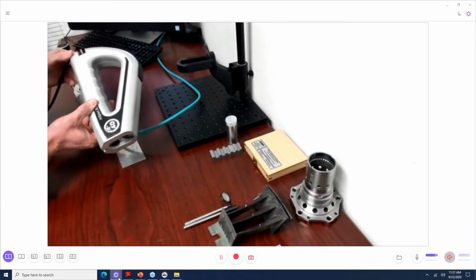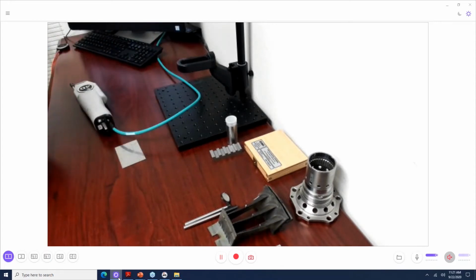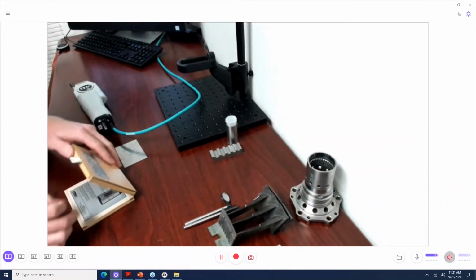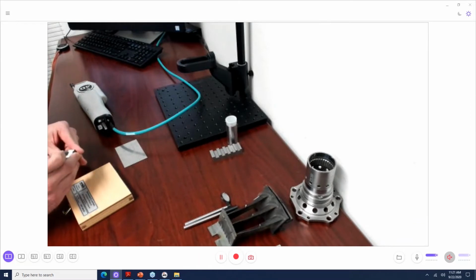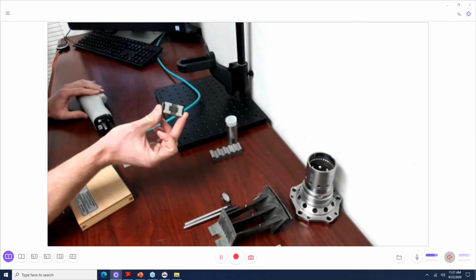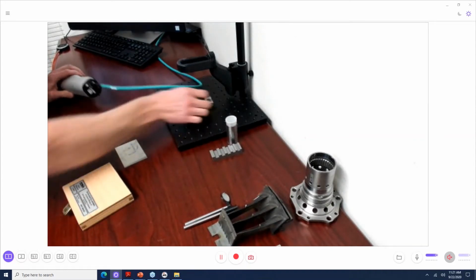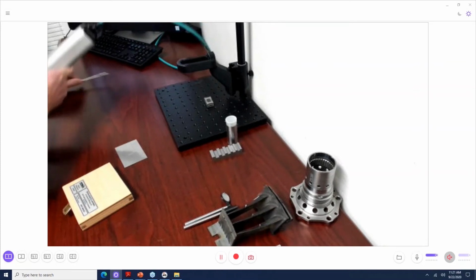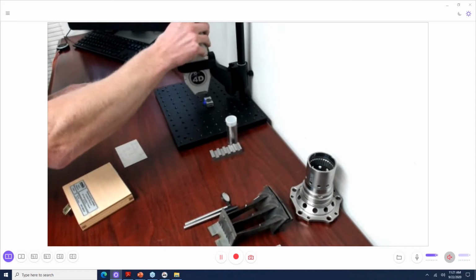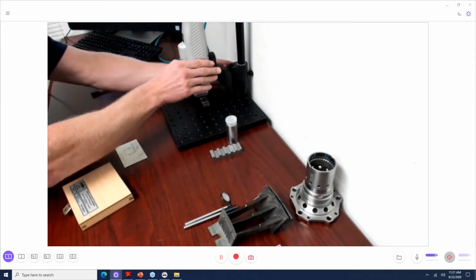I can show you what this system looks like right here. This is the XL version. Sorry, real quick along those lines, they also asked about how we calibrate deep measurements, and Kramer can show you the calibration standard. This is one of the few systems where we use 4 different heights, ranging from 100 to 900 micrometers deep, in order to calibrate the instrument. So we know not just the accuracy, but the linearity of the system over its range. And calibration is super simple, and Kramer will show you that right here.